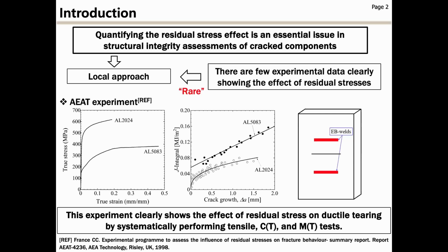However, application of the local approach to combine the mechanical and residual stress is rare, probably because there are few experimental data clearly showing the effect of residual stresses. This experiment clearly shows the effect of residual stress on ductile tearing by systematically performing tensile, CT and NT tests.